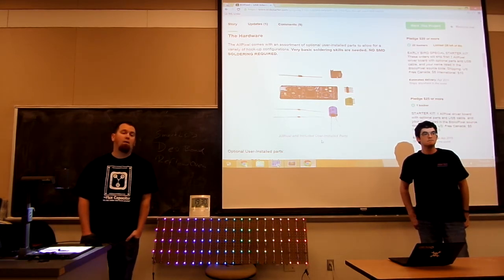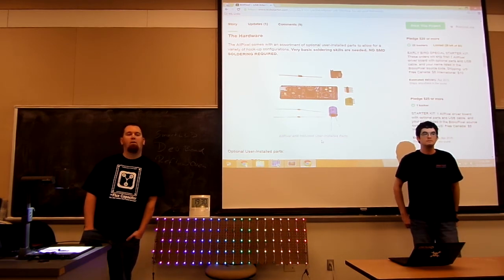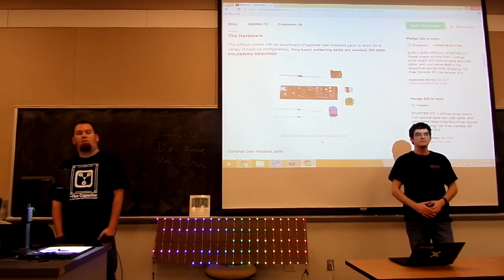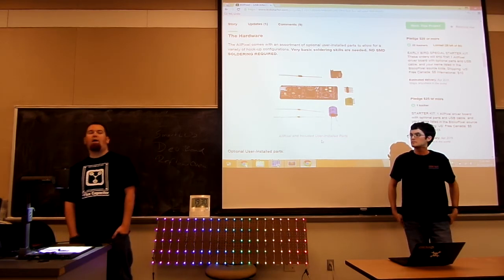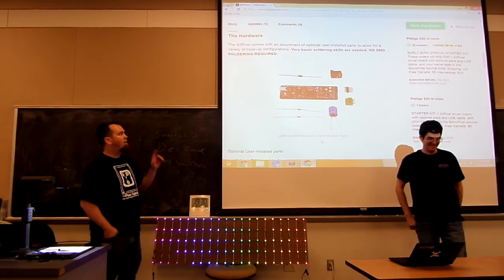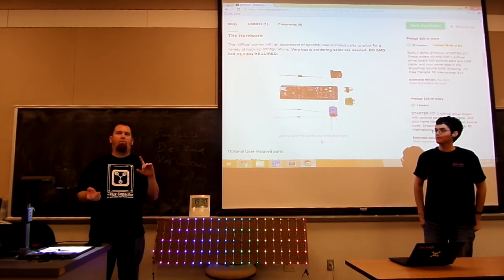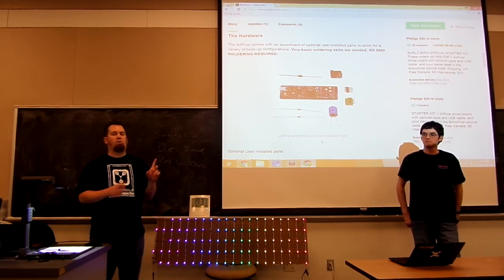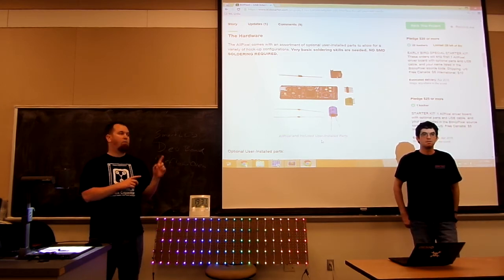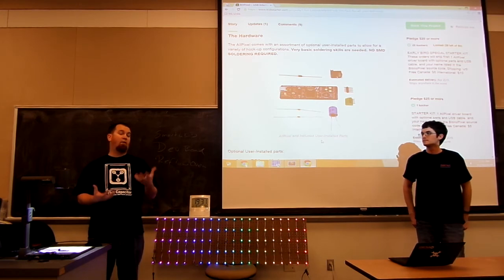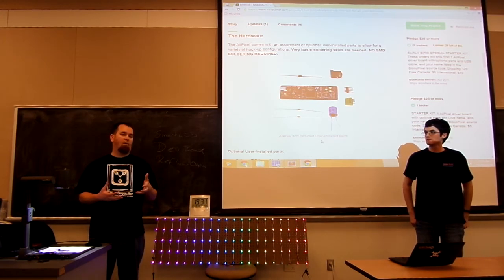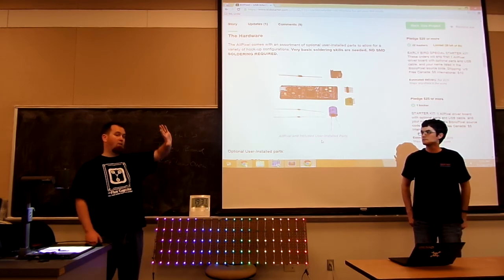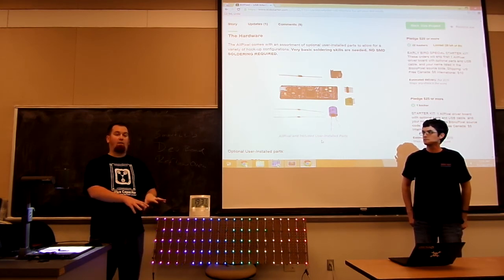What was the processor again? It's an ATmega 32U4. You are using a 32U4? Yes. And you were able to get the USB bus and all that to work well? Yes. That's the other interesting detail. I rebuilt a completely modified version of the Teensy 2.0 Arduino core specifically for this. Really? Yes. The standard throughput on the Leonardo core libraries, or what they would use for the Pro Micro or any of the others, not the bootloader, but the core USB stack,